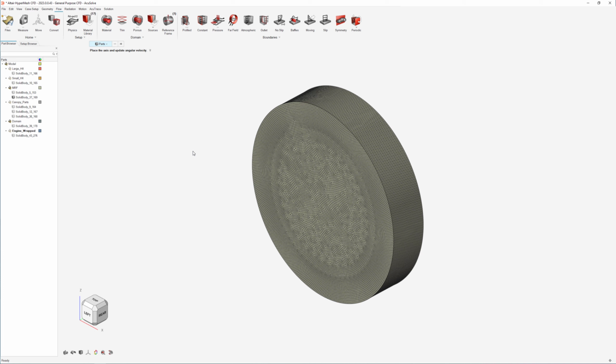At this point of the setup of the steady-state simulation, it is also necessary to activate the controls for the rotating mesh motion and then set a rotational speed of 0. This will allow the restart procedure to be applied and start the transient simulation using as initial conditions the last time step of the steady-state run.